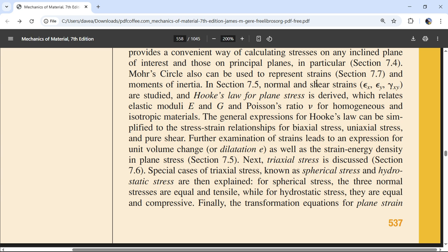So if I have a square chunk of material and then do a positive stress, and again, that's the positive face in the positive, parallel direction. So that's positive y, positive x face, positive y stress, which is just a force on that surface area. Then I'm going to have an equal force on the top in the same direction, and then the opposites down here, and I'm going to get a diamond shape. And when that happens, we get an angle to form, and that angle is just 0.004.